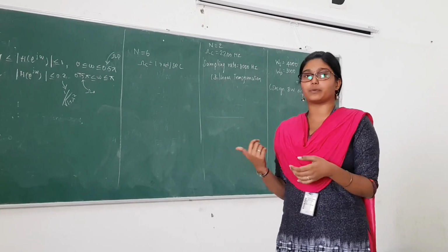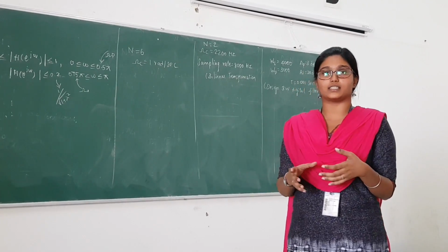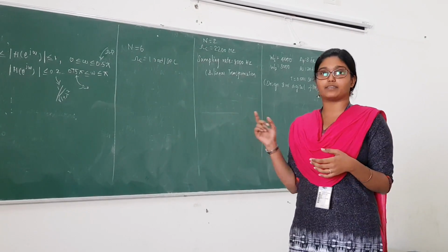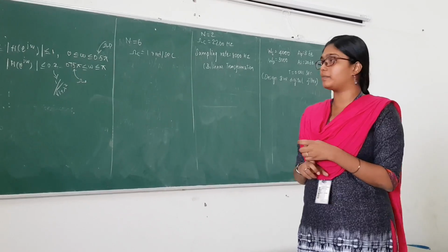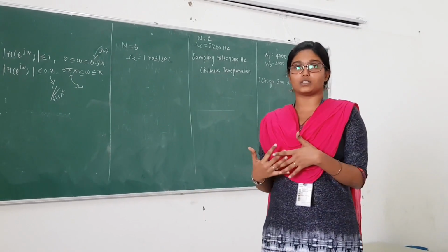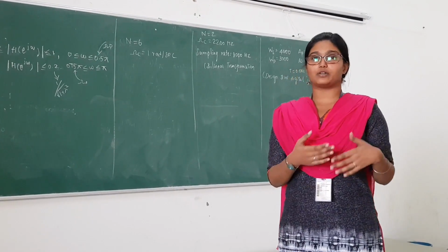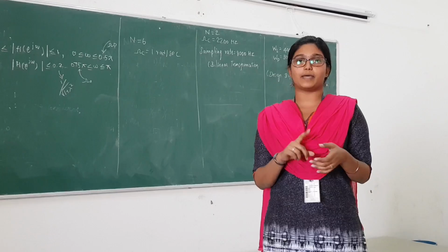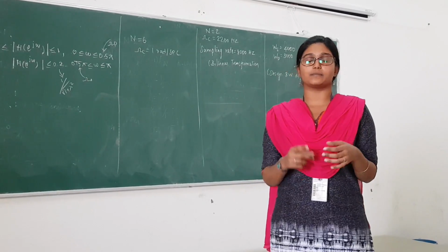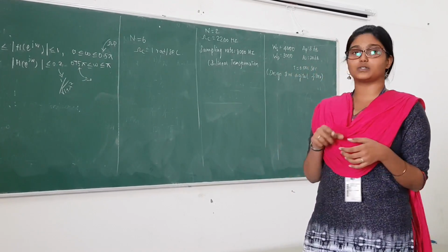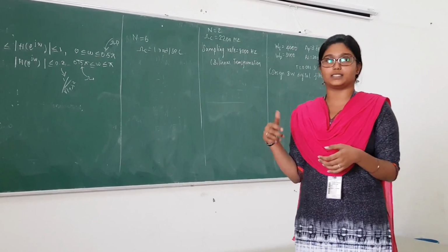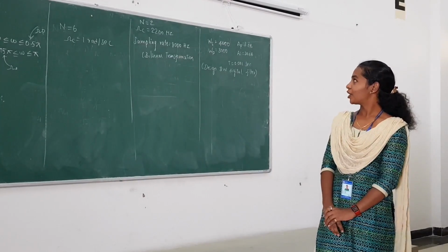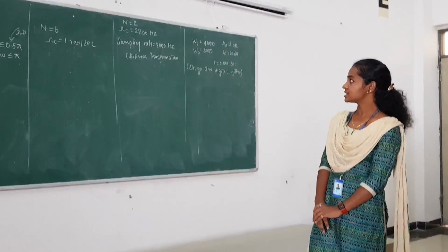So we know from the question that n is equal to 6 or n is equal to 3 according to the question. And then to proceed, sometimes the data given is omega c is 1 radian per second, that is, the cutoff frequency is also directly given in the question. So we have to proceed with the sum according to that, and in the last step, to find H(s), we just substitute s by s by omega c, which is given in the question.